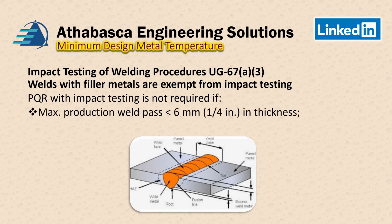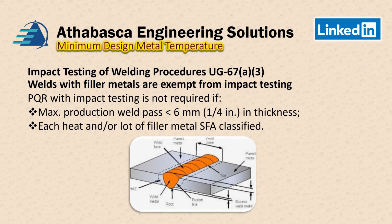If the maximum production weld pass is less than 6 millimeters or a quarter inch in thickness. And the second criterion is if each weld or a lot or combination thereof follows an SFA classification, and it's been impact tested that way.